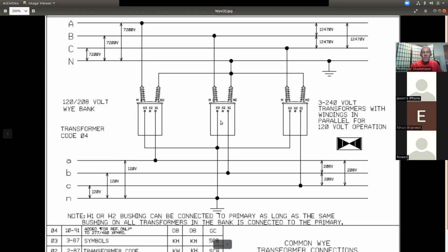Normally, a transformer is going to come 120, 240. Well, how many different voltages can I get out of it? I just said it, 120, 240. So I can get combined. In order for me to make a Y bank, I have to convert all of these transformers to 120 only. Not a hard process. And you as linemen, we're actually going to have to do this out there in the field. And we'll show it when we get back out in the yard.